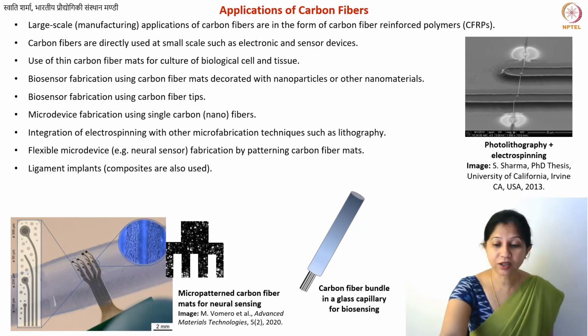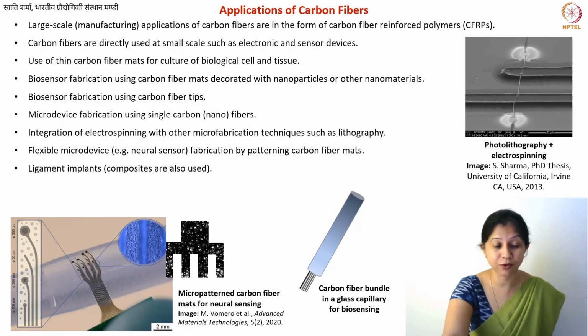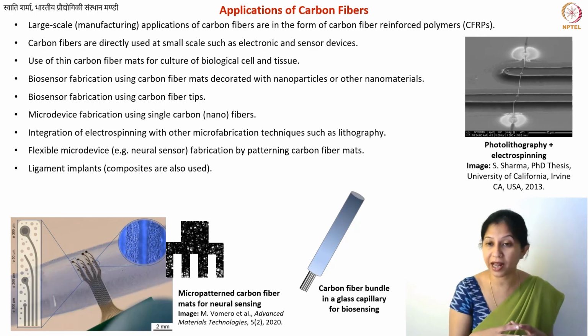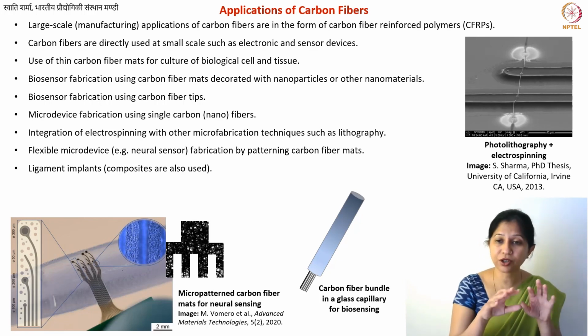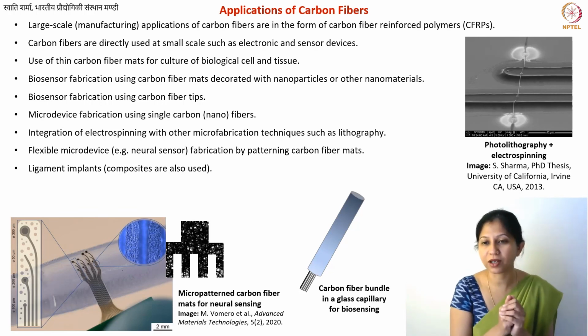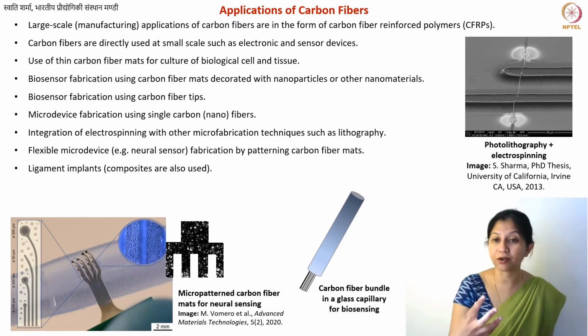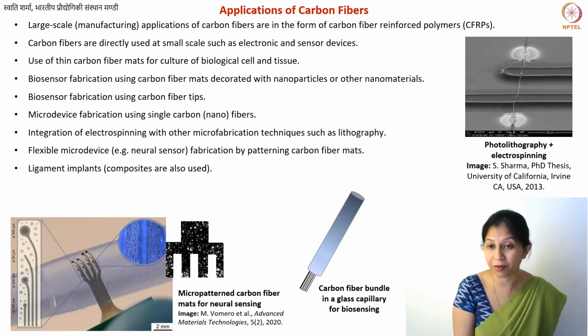Okay. You can also have some biomedical implants which are mainly fabricated using composite materials, because they are load bearing and they also need to stay inside your body. The problem with carbon fibers is that they do not degrade. So if you make a ligament implant, for example, ligament or tissues can grow nicely on top of it. It provides a template and the tissue can grow nicely on it. But the problem is that afterwards you will have to surgically remove it, because it will not degrade and excrete out of your body. So you have to surgically remove these carbon implants.